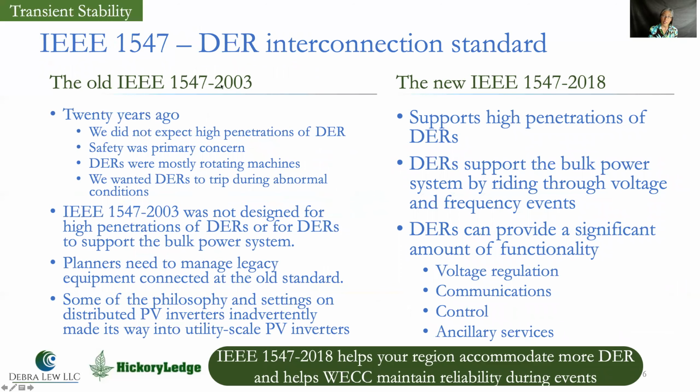The old IEEE standard was designed 20 years ago, back when we didn't expect to have high penetrations of DERs, where safety was the biggest concern, and where we wanted DERs to trip offline if there were any speed bumps on the grid. So just trip offline, get off the grid, because we were afraid that it might accidentally energize a downed part of the distribution system.